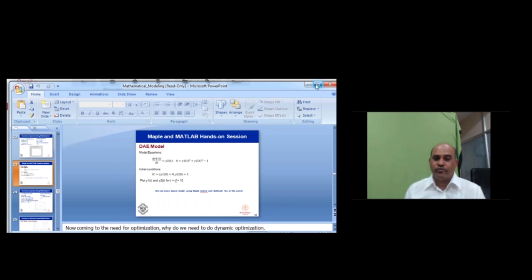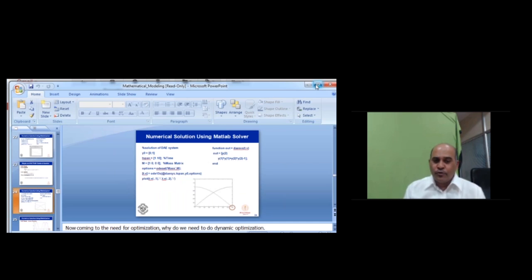When I have used the MATLAB solver ODE15s here, which is meant to solve such equations, you have to form a mass matrix. Just learn how to get the mass matrix. Make a function again and pass as arguments the options with the mass matrix as well as the tspan and initial condition, and you will get this result.